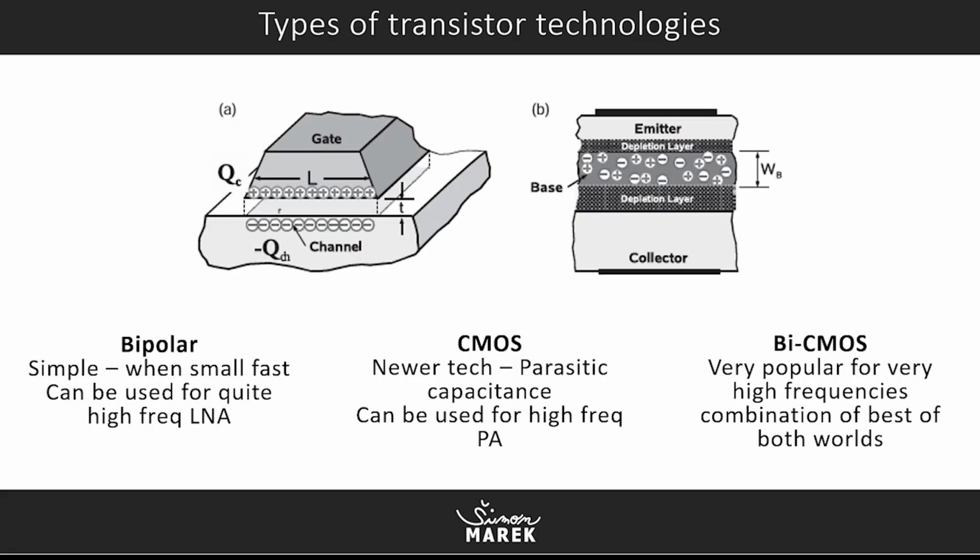This is good for a few gigahertz range, and there is hybrid technology, which is BiCMOS technology, which is a combination of both worlds and has the most interesting parameters, and it's very popular for very high frequencies together with proper choosing of your good substrate.